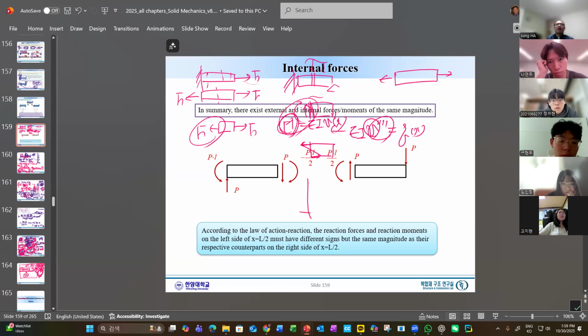Because we always have a stress strain curve like this, and this is the yield strength. So at any point, if the stress reaches this, then the material starts to fail. Yield, plastic, and structures no longer function as a structure.